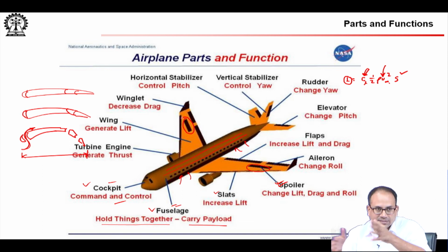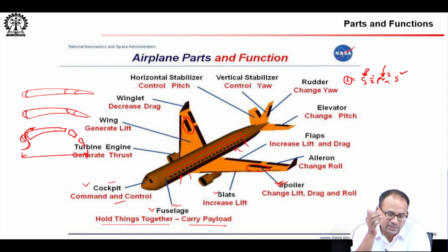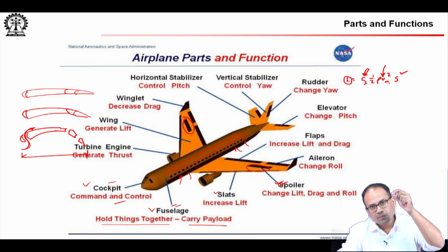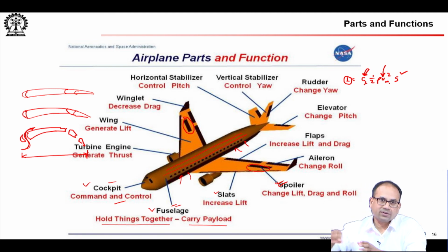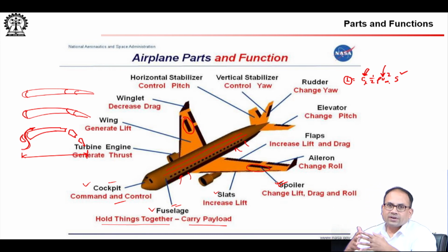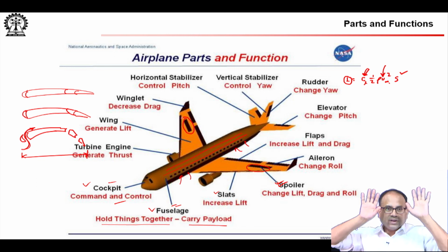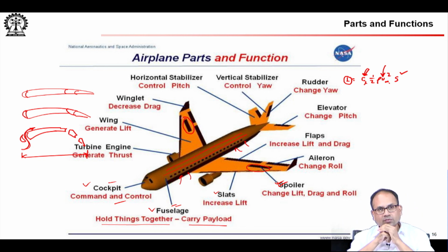You will see how sensitive drag is to the lack of streamlined shape. Ascher Shapiro, in that series of videos on the National Committee for Fluid Mechanics Films, shows a very interesting experiment where he shows that the drag on a wire of a small diameter is the same as the drag on a streamlined airfoil shape, even though the airfoil thickness is quite a bit. So, the streamlining of objects has a very significant effect on drag reduction. So, if you open up the spoilers, you have really thrown your streamlined design out of the window, and the drag on both the wings increases immensely.